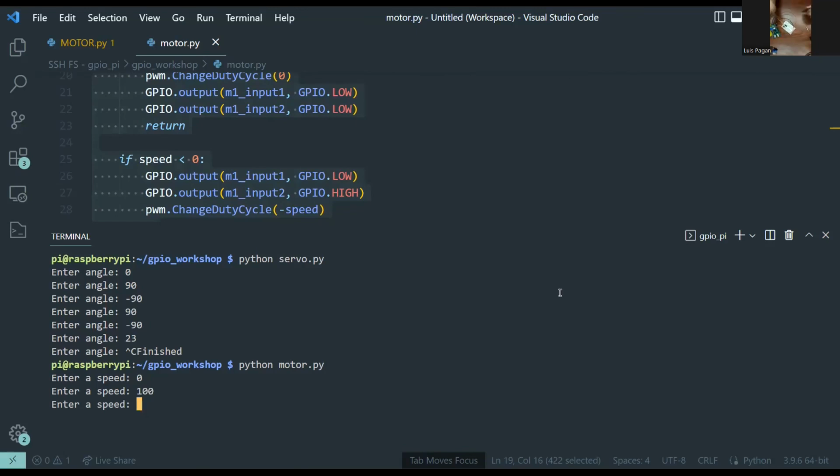And it's not working. So let me debug my circuit really quickly. Power's going in. That's grounded, that's powered. I have found the issue. I don't know why I connected the signal wire to the ground. Don't do that. Be better.